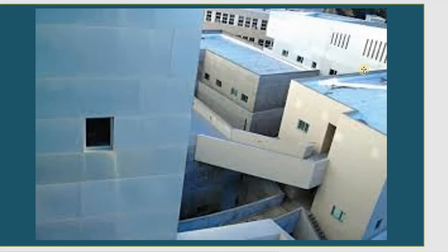Okay, so let me give you one example. This is a building, and this is another building. They create an access so people can go from this building to the higher building. And you look at this, they have nothing to support it. It is so dangerous. The first problem is that because the buildings are very close together, they need a very special fire-rated wall here and here, because they are so close together.